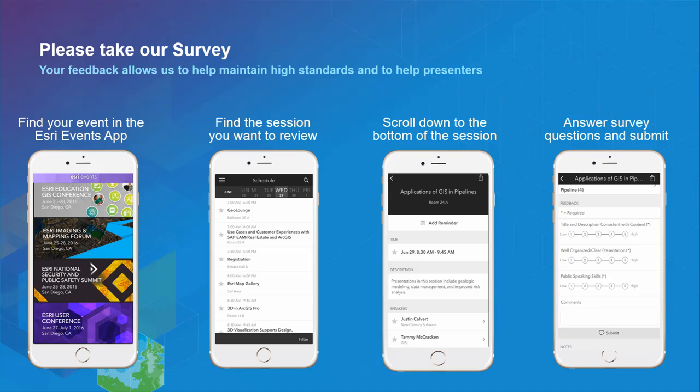So you can do things like add control points at vertices, and what that would do is you'd still technically be drawing the same boundary twice, but if it was a dashed line, using the control point functionality, you'd get those dashes in the same phase so they wouldn't cancel each other out. Yeah, so you could do alternating dashes then. So you can do all sorts of things to make things interleave if you desire.